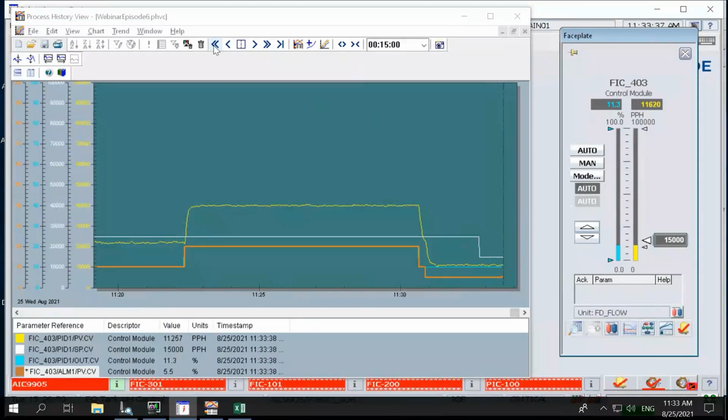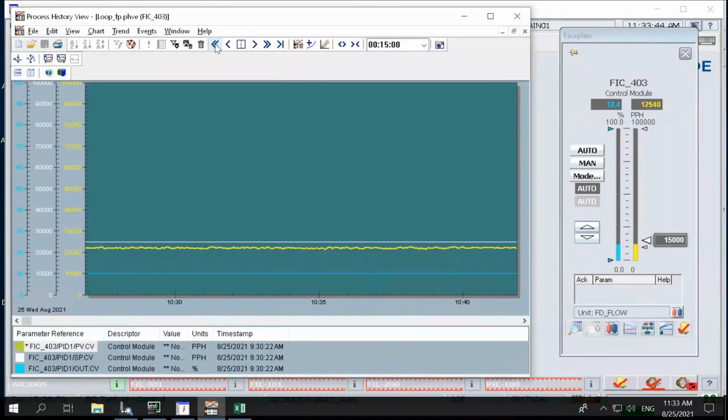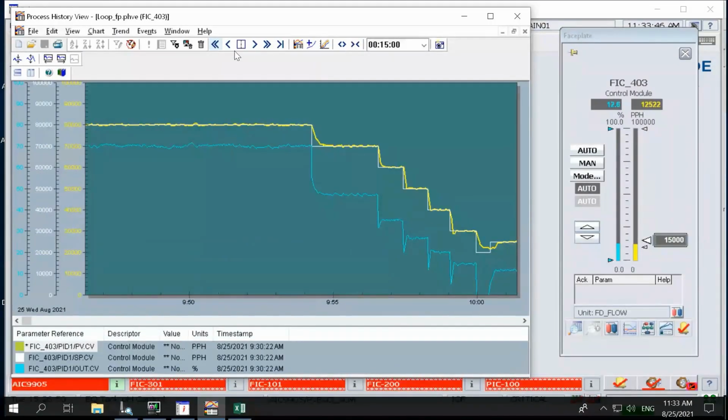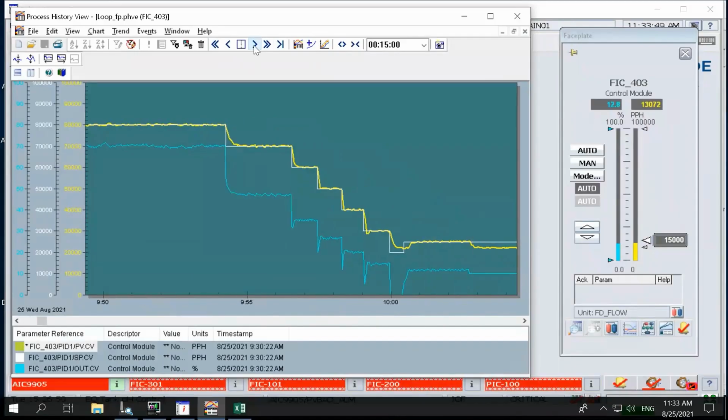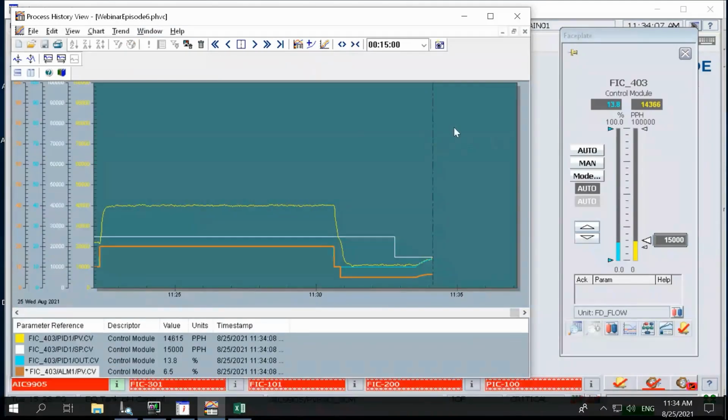So before I do that, I'll actually go back to this chart here. And I'll show you some set point changes I made without the characterizer. And I had tuned it up at the upper end where the process is less sensitive. And I made equal set point changes down. And you can see that it becomes less and less stable. Let's go back to here. Okay. So now I put it in automatic mode.